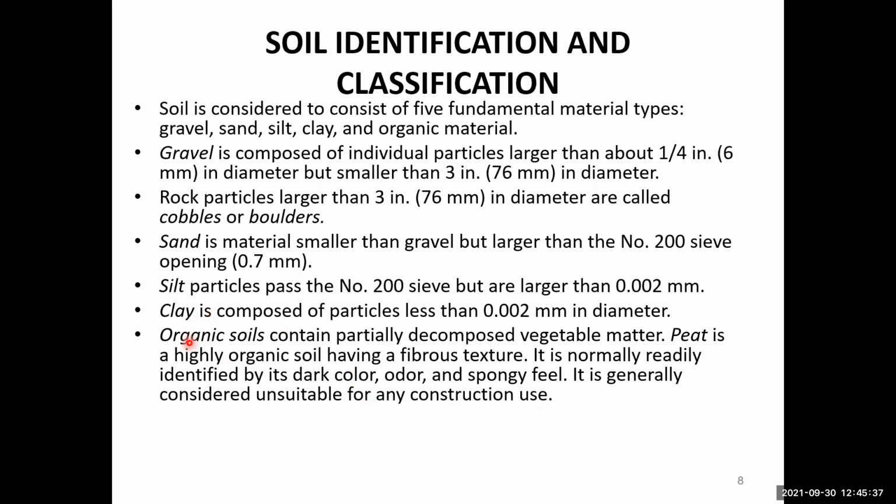Normally for construction use, if we find organic soil, we have to remove that organic soil from the site, because these types of soils are unsuitable for construction, since they cannot take the loads. They can decay, and if we want to place any structure on those types of soils, it will be very difficult for them to withstand the loads. Although these soils are good for agriculture, good for growing plants and crops, they are not good for civil engineering matters.